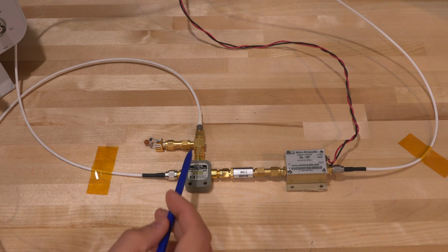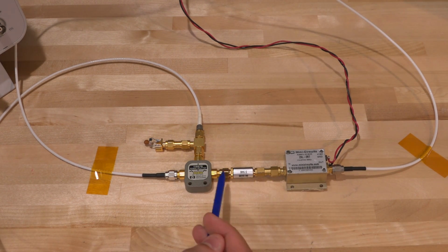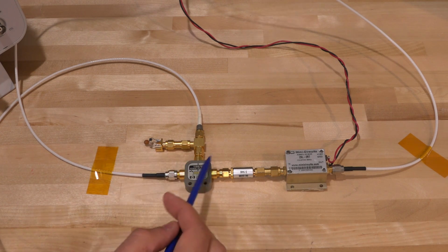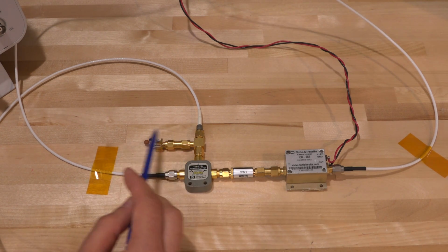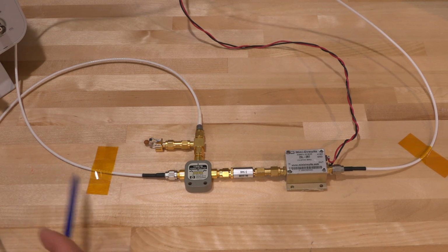And as frequency increases, the impedance looking in this direction is always going to be maintained at 50 ohms no matter what. And that allows us to purely focus on the nonlinear and also frequency dependent behavior of the impedance here that's loading our function generator. So let's go ahead and look at all of this together.